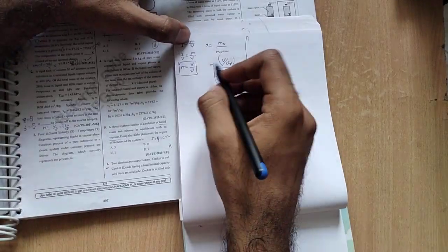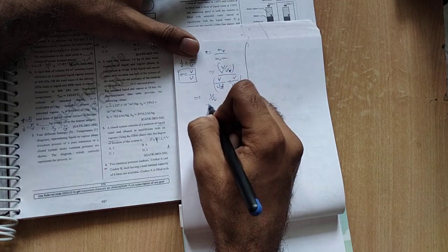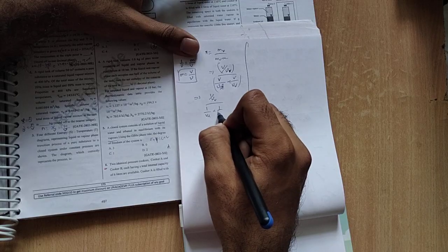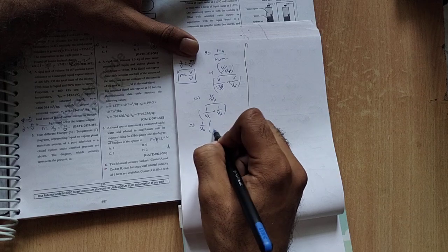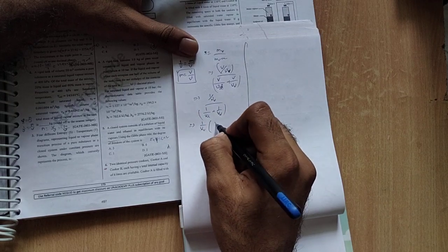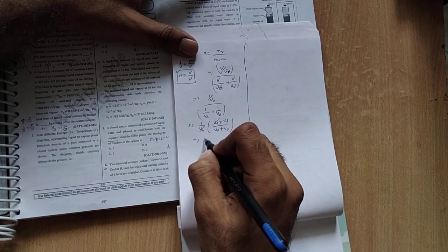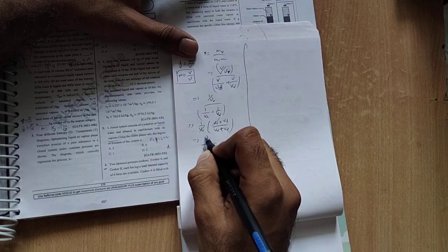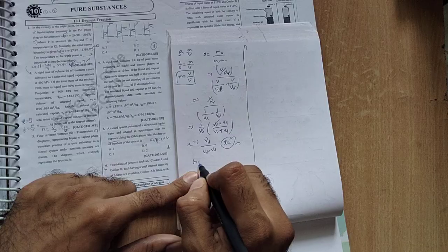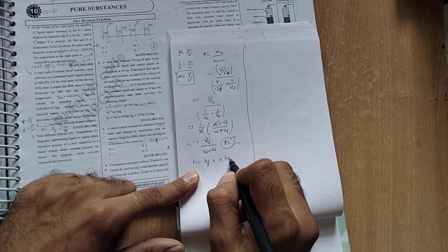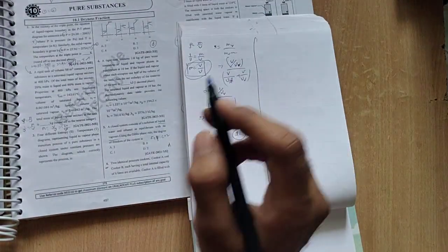Wow. By this we can neglect the entire V term. So x equals 1 by specific volume of vapor divided by 1 by specific volume of liquid plus 1 by specific volume of vapor, which simplifies to V of liquid divided by V of vapor plus V of liquid. Here each and everything is given. Calculate the x value, and after that h equals h of f plus x times h of g minus h of f. Wow, such a good question, guys. Basic thing only, just use common sense.